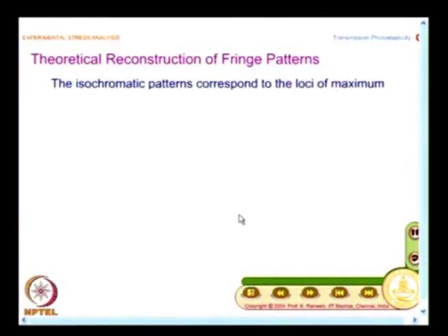And even the thickness variation, you can do it by a very simple mathematical step. You do not have to worry that depending on the fringe gradient, I should go and tell the program to make the thickness so much, nothing of that sort is required. And how do I do the theoretical reconstruction? This is what we will see.